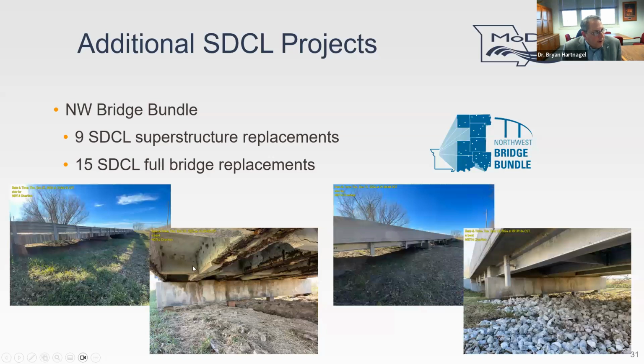Around here, we call these U-beams or bathtub bridges. Essentially, they were lightweight concrete, precast U-shaped beams that were set side by side and tied together. A very shallow superstructure, as you can see. But the lightweight concrete was kind of porous, and these weren't pre-stressed, they're just reinforced. And so you can see the concrete spalling off after chlorides got to the reinforcing steel.